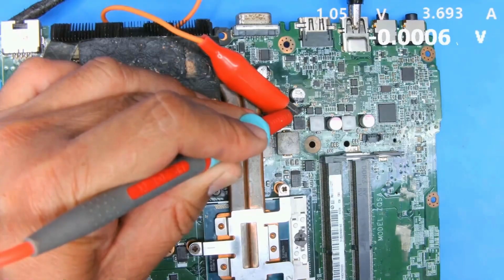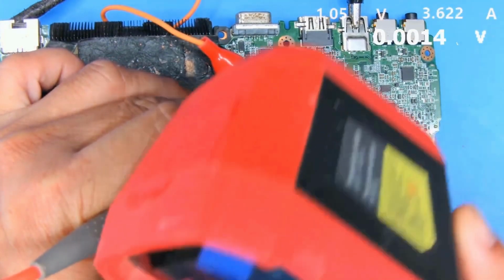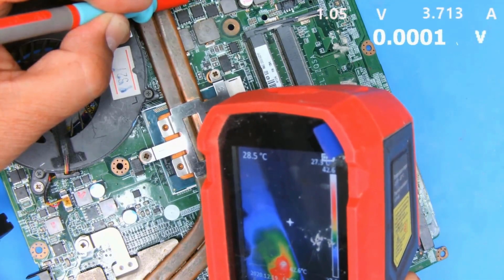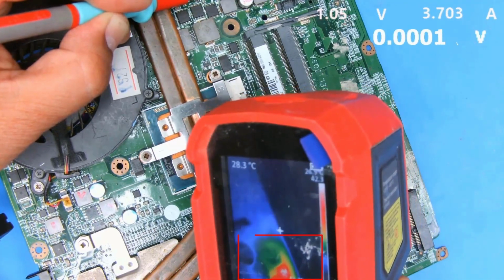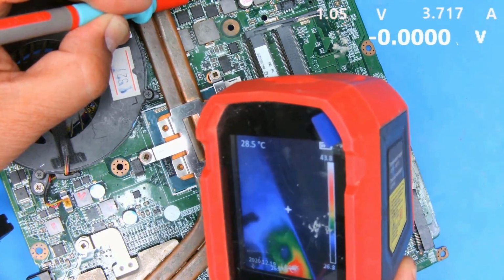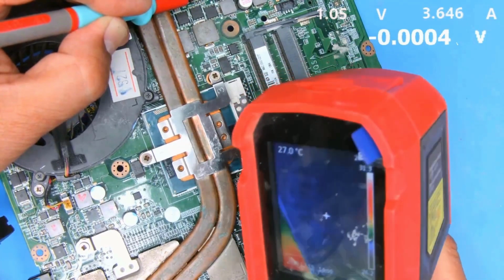I recommend using an infrared camera. Just keep supplying power and use the infrared camera to see where the heat is coming from. It's about 45 degrees. The infrared camera will clearly show it. If we point our hand, you'll definitely see our finger on the screen. You can observe where the precise position is, but it's not exceptionally clear.